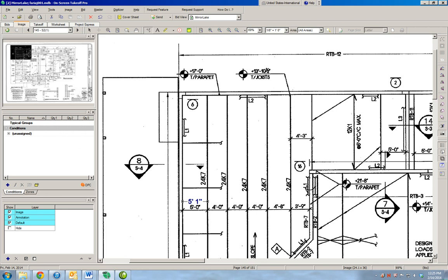So now we can go to Excel and enter the code that we have for this joist: 05210 600 068, and then metal joist 24K7. So we have the unit of measure is linear feet, the material cost is 8.50, the labor cost is 1.43, and then the equipment cost is 0.73, for a total of 10.66.